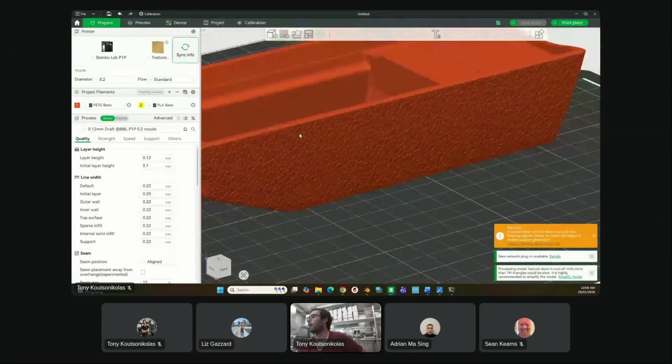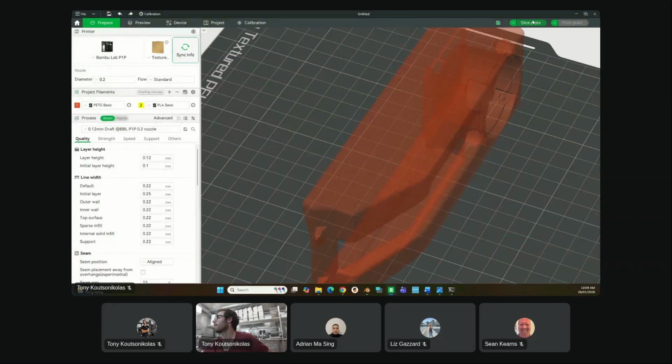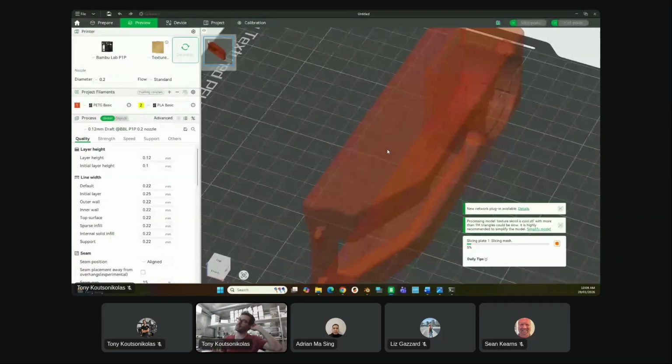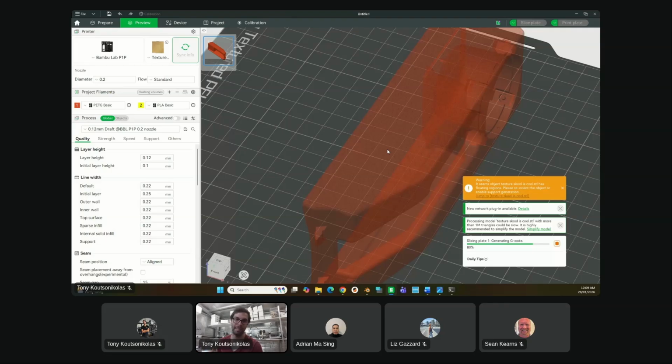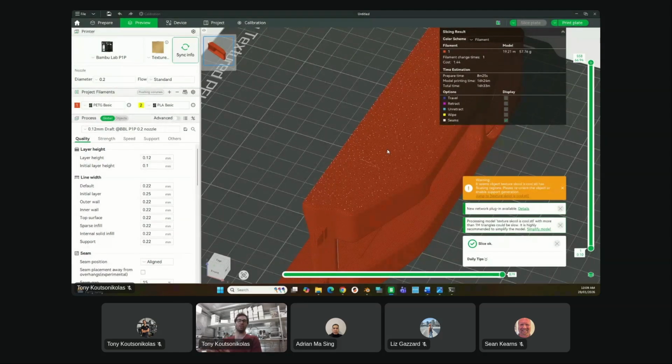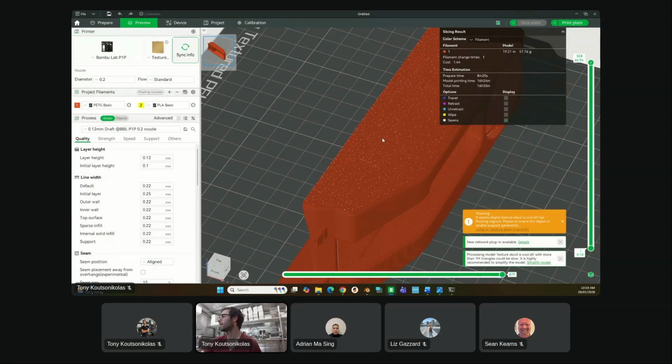But if I turn it this way, this is where you get the limitation of 3D printing, orientation-wise. That texture just can't be applied in the same way in this direction, because the texture height might be less than a layer, or about one layer. This is where you have to figure out how to apply the texture but make it print in a uniform way, because the whole point is to make your eyes seamlessly gloss over it and think, oh, this is a beautiful part.